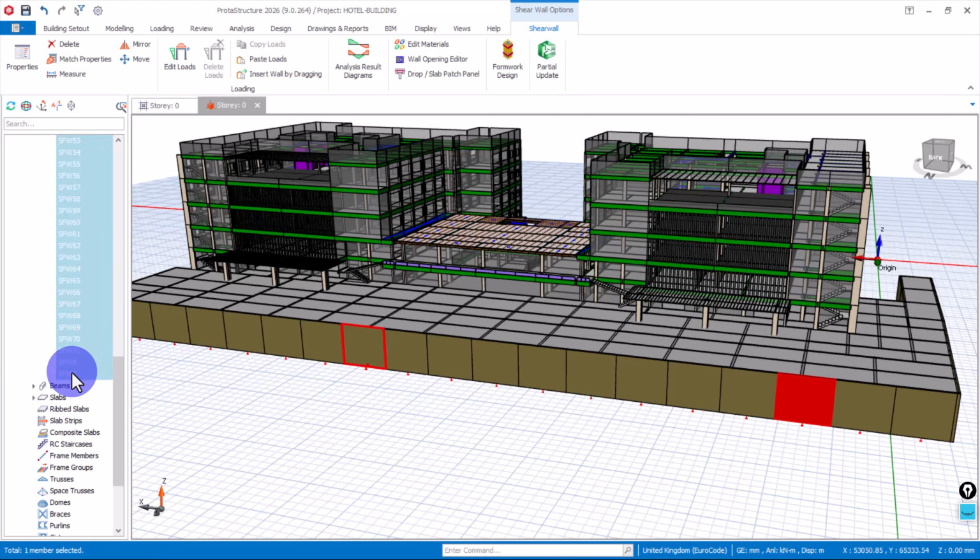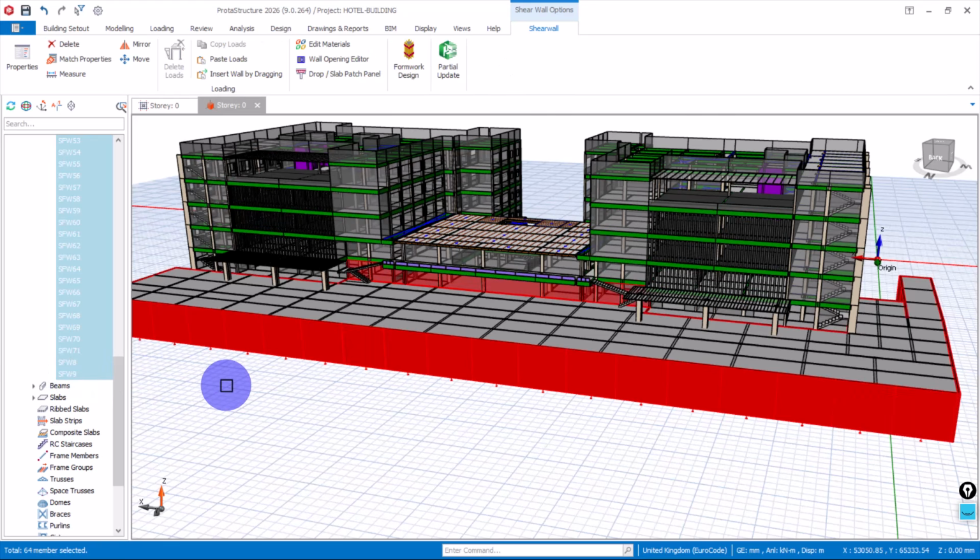I'll then click here and wait for that to select all the walls together, and then we will skip wall 18 once it is done selecting everything, because if you paste again on wall 18, you are doing double loading, which is a double soil load on that wall, and most times it might fail, and that's what they call over design. So you have to use the right load that is meant for the wall.